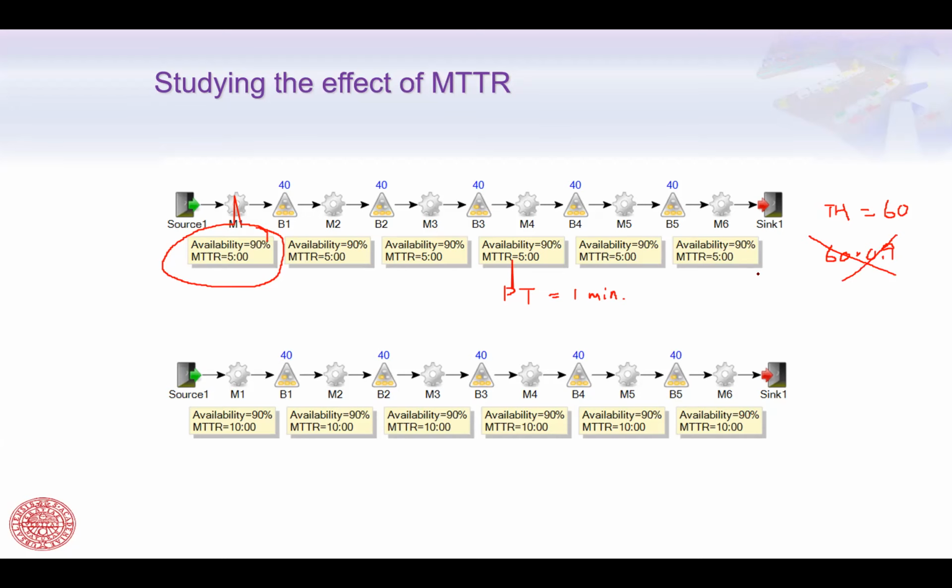This will be wrong because of the connecting effect of different availabilities. When you have a longer line, the availability issues propagate to each other, which makes it even worse than 0.9 if you just calculate one of them. And what throughput you will get is very much determined by your buffer size. So this is what my demonstration is about. Let me know if you have any questions.